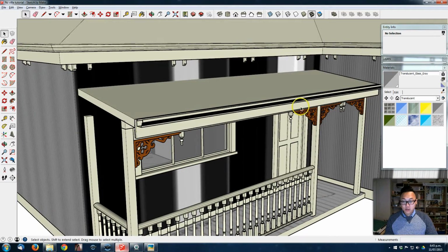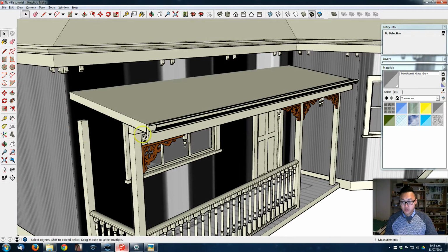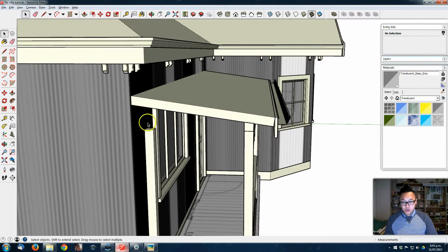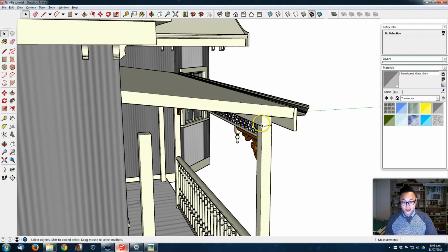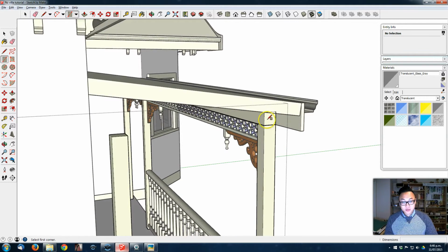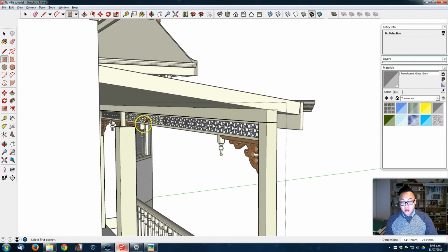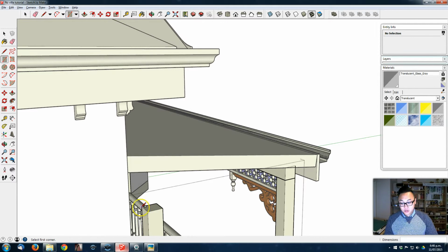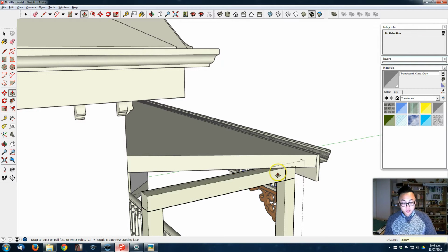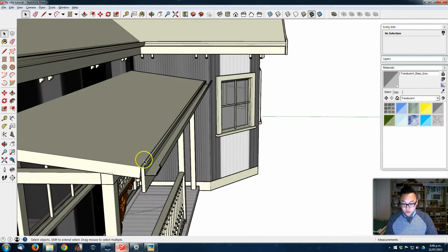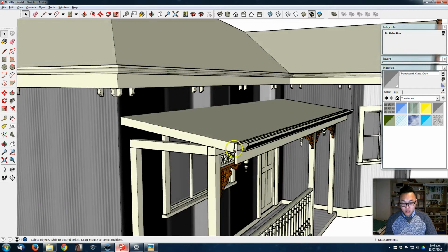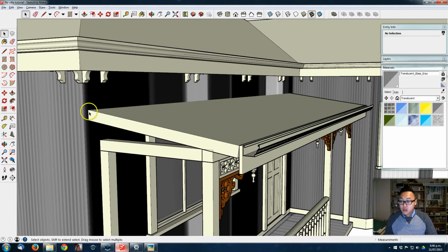Okay, I think we're gonna also build a barge board. Oh wait, I forgot to create a beam here. Just get in, create a rectangle, extrude by 90. Double click, make it a group. So now we get a beam here, and we're gonna create a barge board. So it's the same as this.